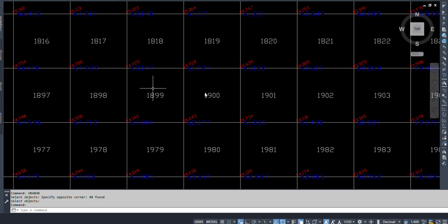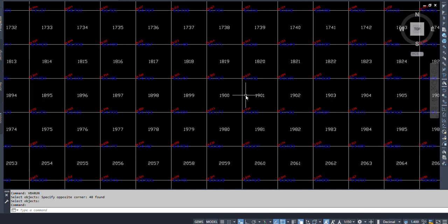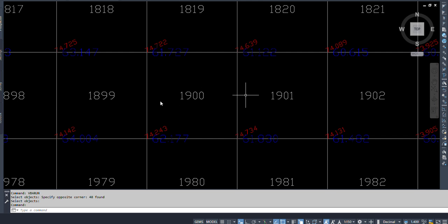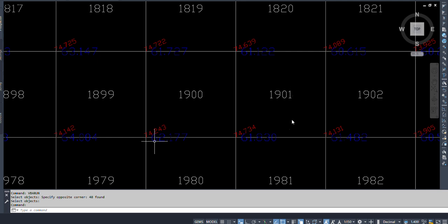This method is specifically used for area grading and construction earthworks. At the initial stage of the survey, you have natural ground levels, meaning the earth area without any disturbance. After the proposed finishing, you have to calculate the volume of how much cutting and how much filling. For that, surveyors and civil engineers collect the elevations from the four corners of the area, and the finishing levels are also found at the four corners.